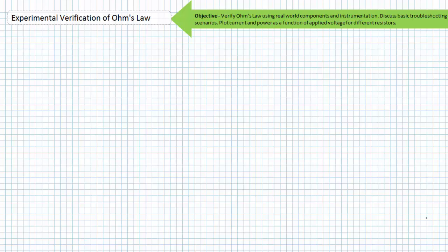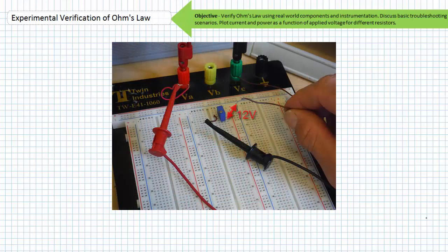Ordinarily, the only voltage drop with a single element in a circuit would be observed across that single element. However, progressively working through the circuit with an open between the resistor and the negative lead of our voltage source, we'd observe the voltage drop at the open. Additionally, opens can be created not just by errant wiring, but also improper placement of instrumentation.